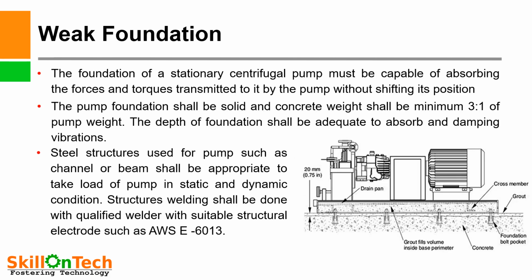Here you can see a picture of the foundation of a pump. This is the grouting, and this is the structural foundation. This is the motor, and this is the pump. So a weak foundation is also one very important reason for vibrations occurring in centrifugal pumps. The foundation of a stationary centrifugal pump must be capable of absorbing the forces and torques transmitted to it by the pump without shifting its position.